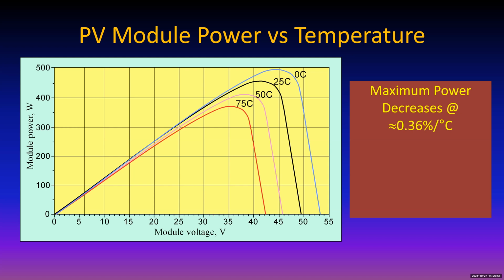And that's important when you get into the design of a system to recognize that if you have 5,000 watts of modules at standard test conditions, you're not going to get 5,000 watts out of that. In fact, in the most recent simulation I looked at for a New Jersey installation, the closest one would come to that was 83% of the 5,000 watts total rating for the array.